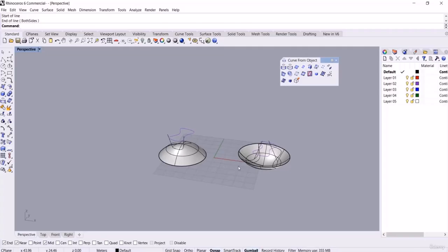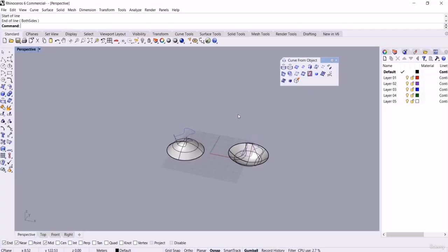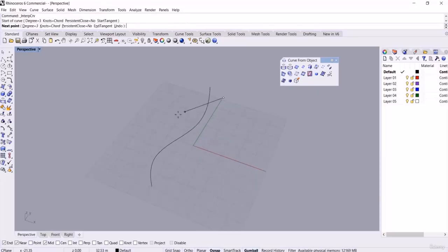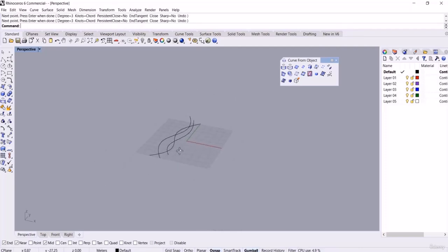So when we are using the pull command, the continuity of the surfaces does matter, and the size of the curve after being pulled toward the surface will be changed. And here I want to introduce one of the applications of pull in the following example. For instance, we got a surface like this. Check this out.